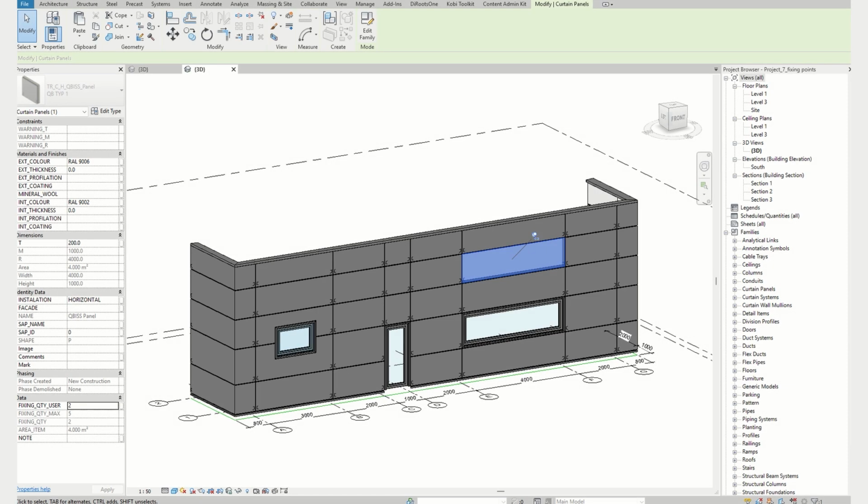We have one last definition left. How do we determine how many fixings are required to hold each panel in place? First, we need static calculation where we can find how many screws per panel are required. Minimum is 2 and maximum is limited by panel modular dimension, because we have C washers pre-installed on overlapping endings. Through these washers, panel is fixed to the substructure. Maximum number is calculated automatically. We put required number from the static calculation to user fit, but not higher than the calculated maximum.